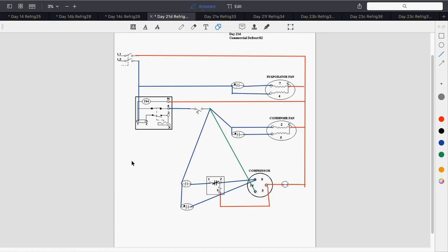So if we had the defrost timer in this one, that and the solenoid, that's where the 3 and the X would bring those tied into the system, correct? The 3 pin and the X pin? Yes, I think one of our other diagrams that I'm going to go over has it, but the 3 would be controlling either my defrost heater, which obviously would have a high limit on it, or the defrost solenoid.